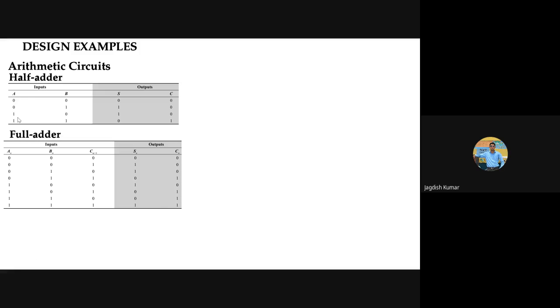So similarly, this will be the truth table for a full adder. You can actually see this. It's a very simple binary addition only. But here is the truth table for that full adder. And then again, you can write down the K map for Sn in terms of A, B, C. So now the K map is going to be a three variable K map.